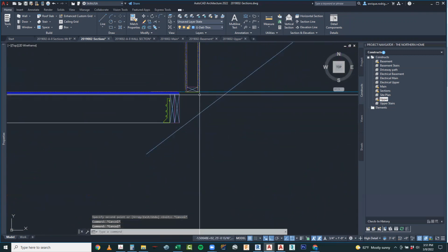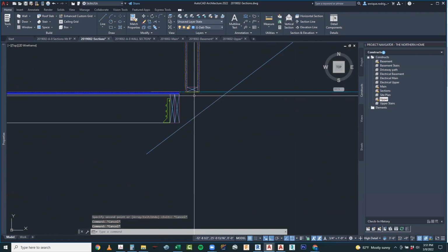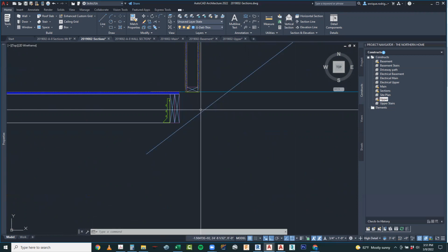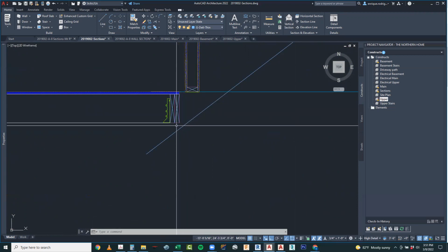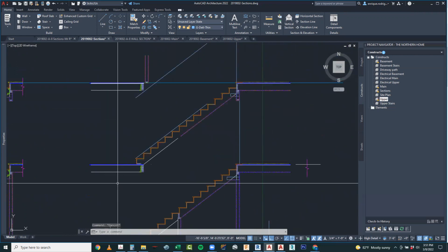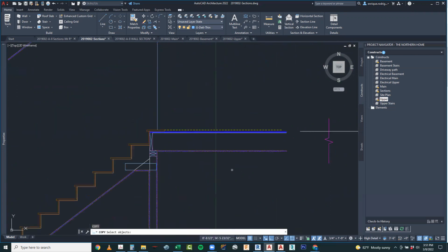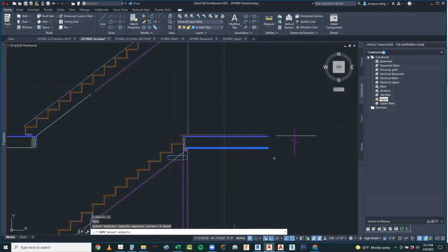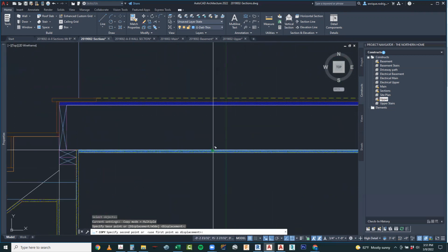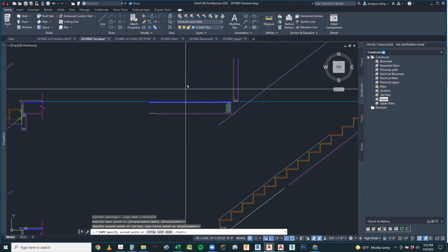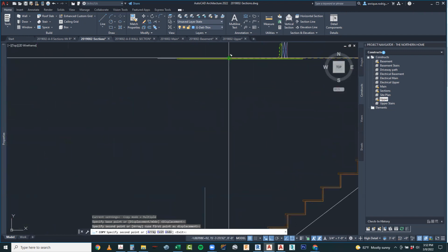Okay. Now, one of the things that I can do is I can now create framing right here and wrap this guy around here. And then we can get drywall underneath this guy. Okay. So let's go ahead and copy our horizontal drywall. I'm going to place it here, and I'm also going to place it underneath this one.